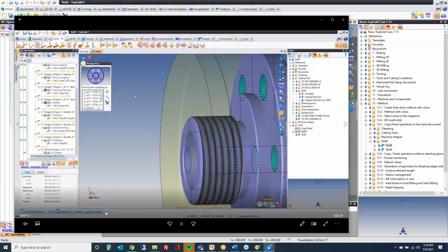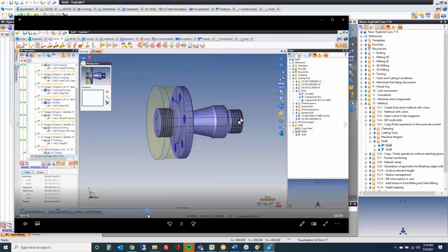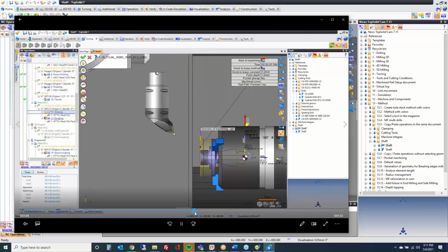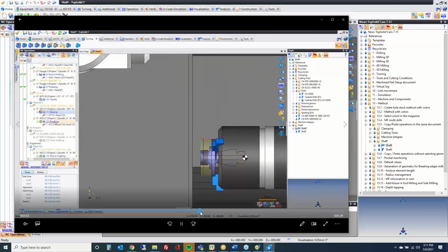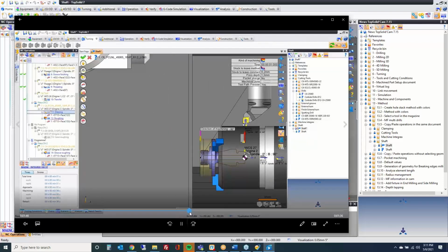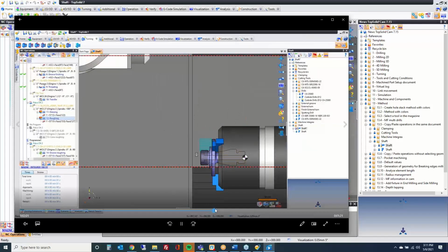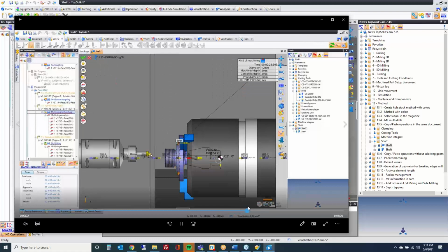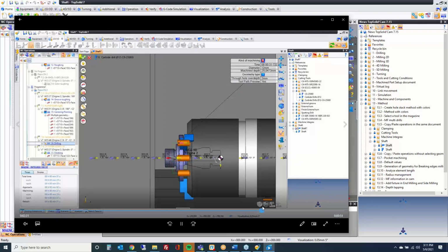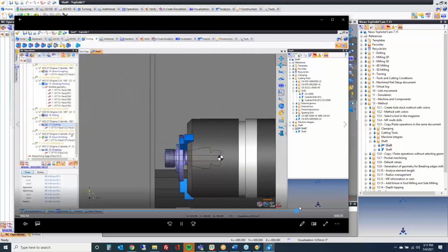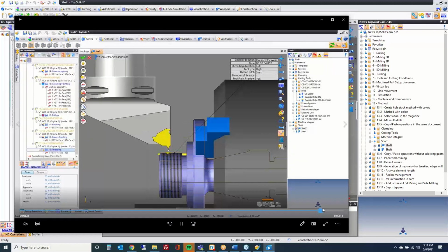And I'll show a sample of that here in just a second. So here we're applying everything. It's calculating. And then about the only thing you need to do is, if it's a B-axis machine, for example, is go through and change tool orientations, but the operation settings are all there. So you have some work to do, but for the most part, everything else is copied over beautifully. And you can just quickly go in, apply everything, and off you go.